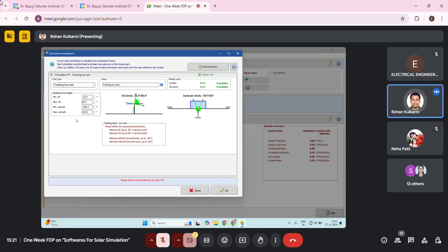Once we know that we need to set up the solar plant, depending on the area you have, we need to select the particular orientation. If you don't have a bigger area available, you can go for the dome structure. You can also go for the tracking one, but for smaller areas you need to be very careful about the support system. You can give elevated support, such as some pillars, and install the tracking system. If you ask the solar manufacturers, mostly they won't suggest the tracking system. The only reason is the maintenance.